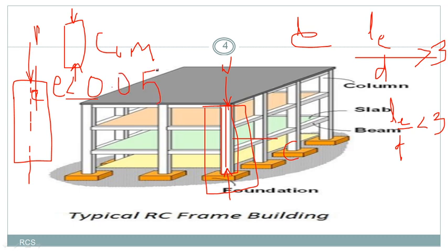0.05 times D, then also we can call it an axially loaded column, subject to the condition that it should not exceed 20 mm eccentricity. It should be less than this and should satisfy this 20 mm criterion also. Then we can call it an axially loaded column. If it is exceeding this value, we can call it an eccentrically loaded column.